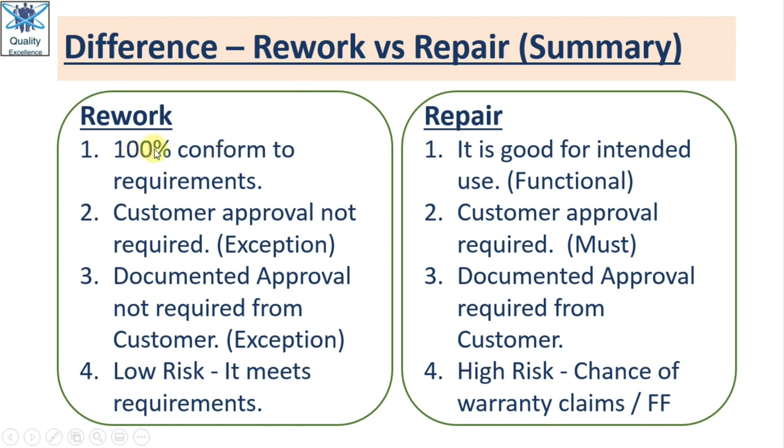In rework, 100% conformance to requirements is there. After carrying out rework activity, it will be 100% conforming to the requirement. And in repair, it will be good for intended use. It will be acceptable but not 100% conforming to the requirement. The second is customer approval. Here, if you carry out rework, customer approval is not required. In some exceptional cases, if the customer specifies, then we have to inform them about the rework.